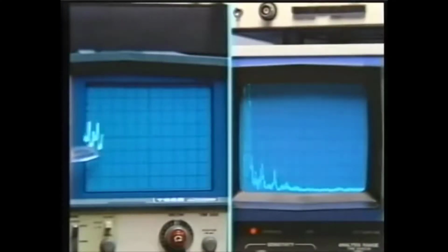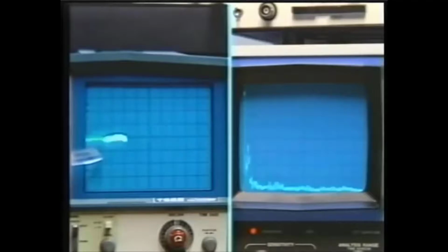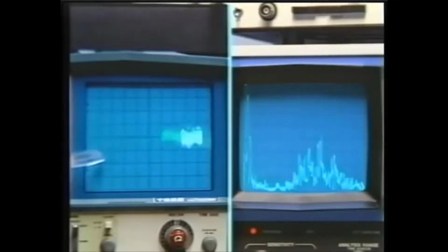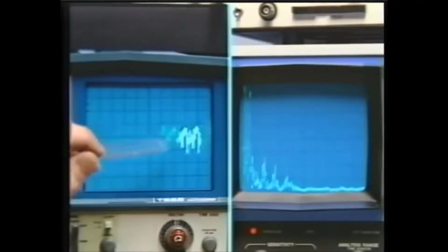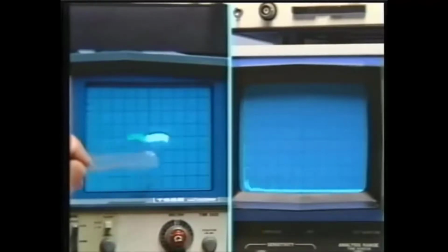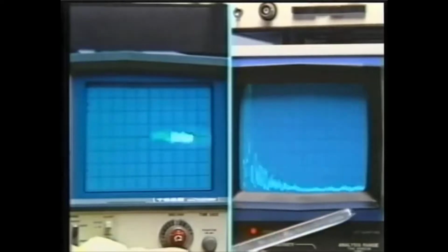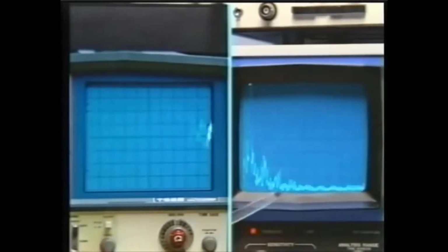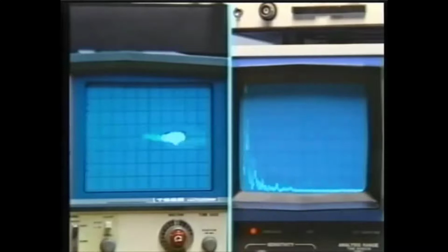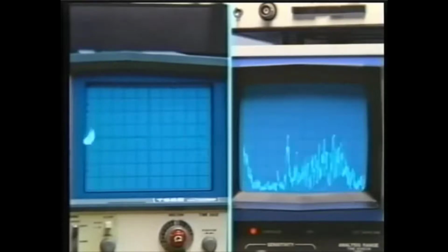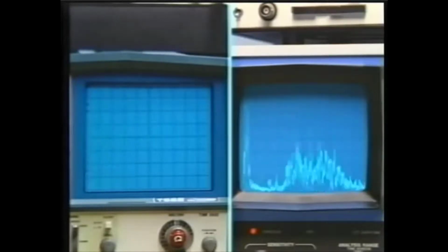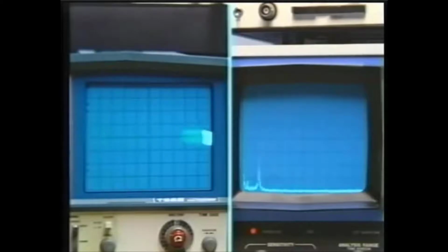As we look at the scope, again, the time waveform is extremely complicated. It seems to have some periodicities in it, although they're short-lived, and then it goes on to some other periodic chunk. And over in the frequency domain, you can see as we extend from 0 to 10 kilohertz that as I speak, there are transients that have spectral content covering that entire band. I can try some simpler signals. A whistle is almost a sinusoid, but as you'll see, isn't terribly sinusoidal.